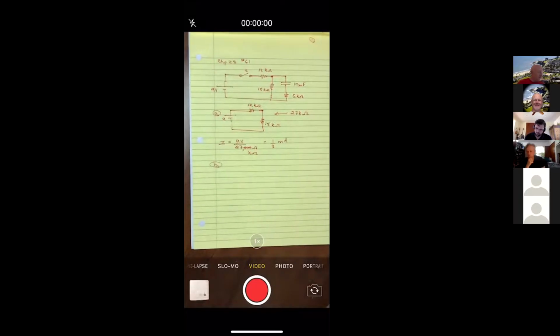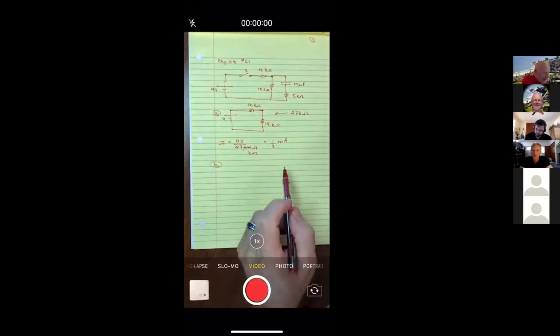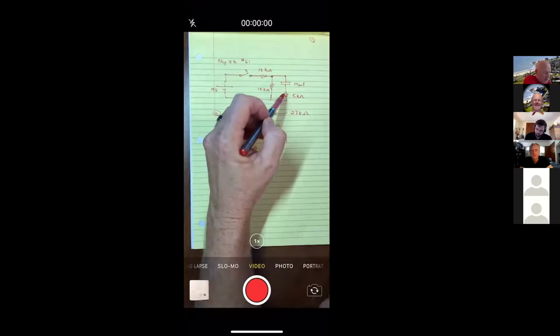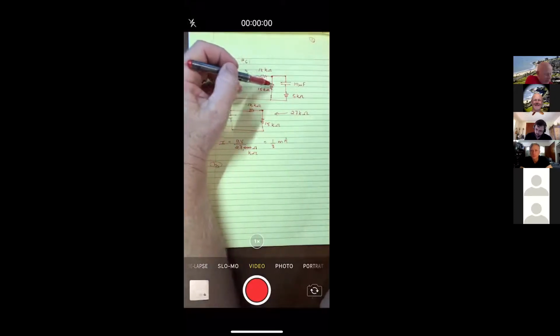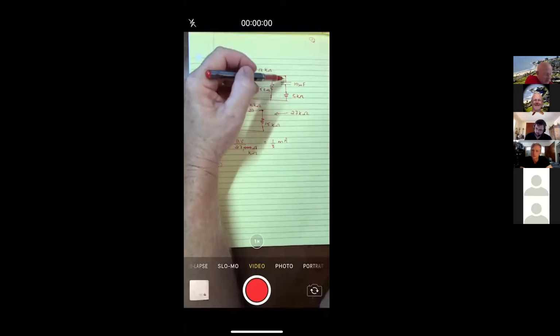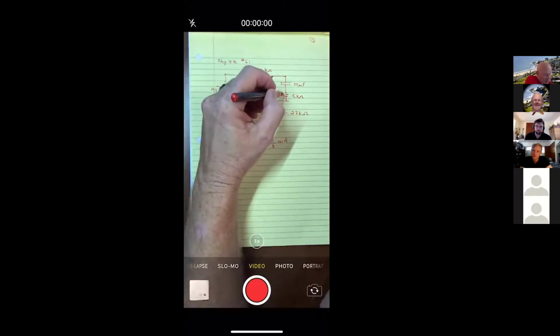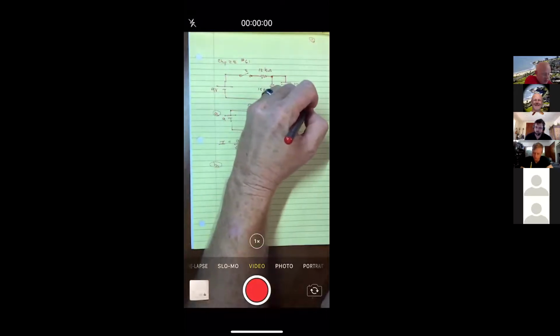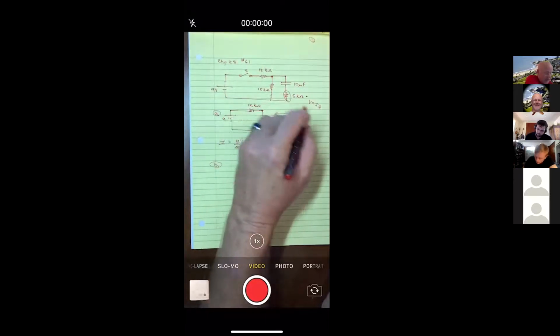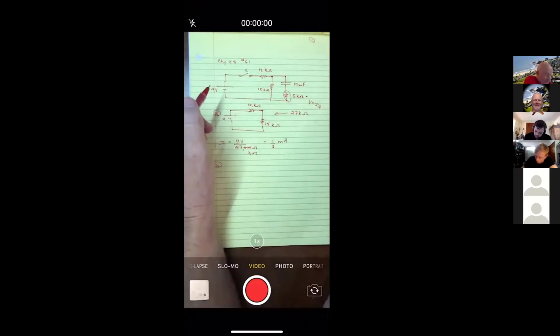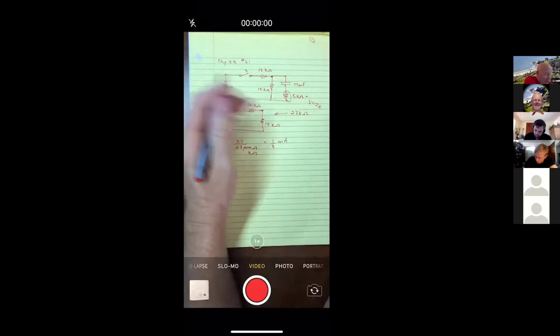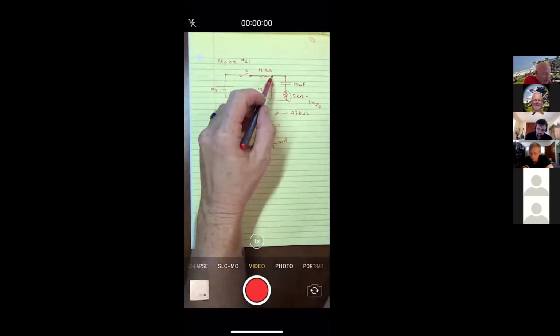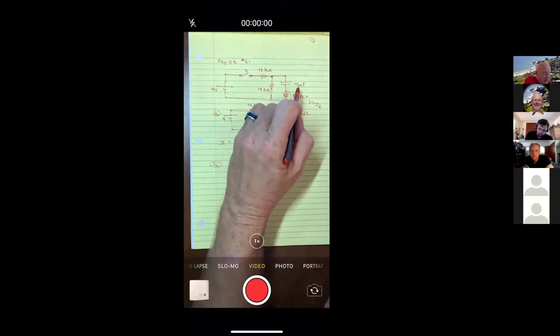Now, let's come back to that important phrase. It's been closed for a long time. All right, so closed for a long time, again, means no current is going through here. And these two are in parallel. See, if there's no current flowing through here, then the voltage on this resistor is 0. Remember, the voltage on a resistor is its current times its resistance. And I'm saying there's no current here. So the part that is stopping the current from flowing is all the voltage on this capacitor.